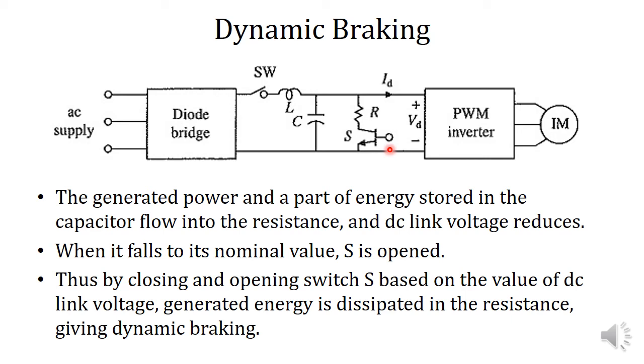The only disadvantage of this method is that the generated energy is wasted in the resistance R without using it for driving any other load or any other purpose. But it is a very simple method of braking of VSI fed induction motor.